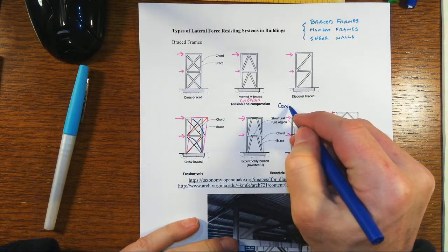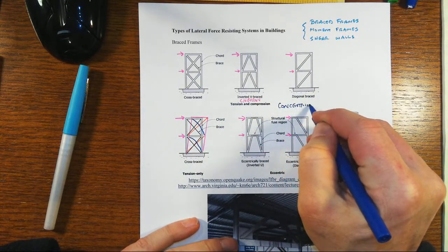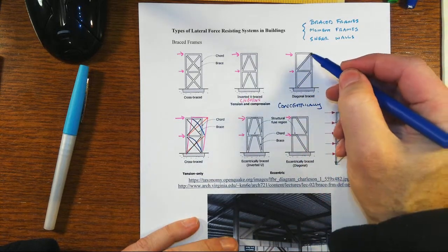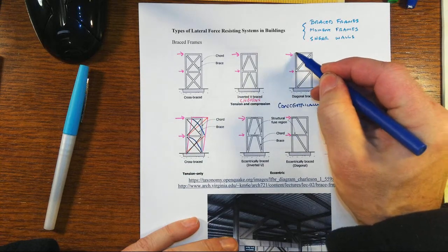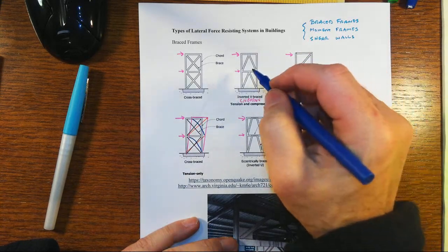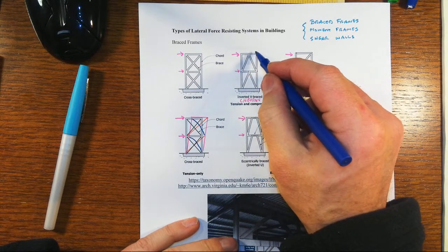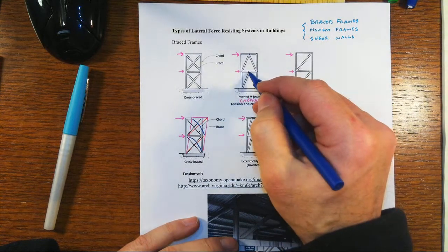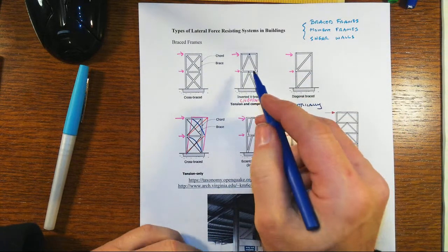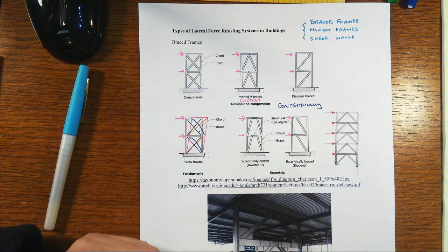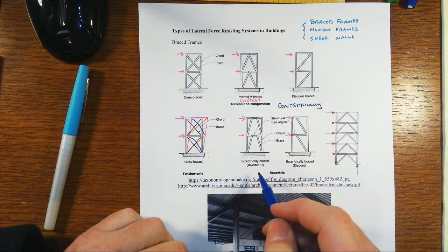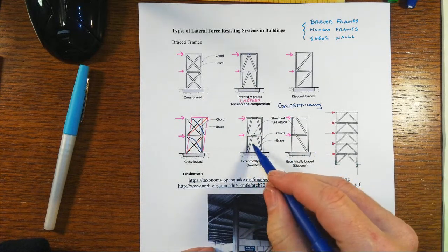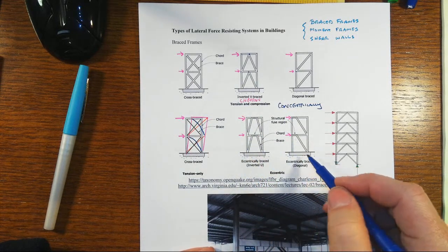That would be the broad category, because the line of action of these braces passes directly through that working point that is the joint of each of those connections. Particularly here at the crown of this inverted V, those diagonals will cross through at the same location as the longitudinal axis of the beam, whereas if we were to push that apart like we see in this eccentrically braced frame, that would have two of them, versus the other one here just has one single diagonal.